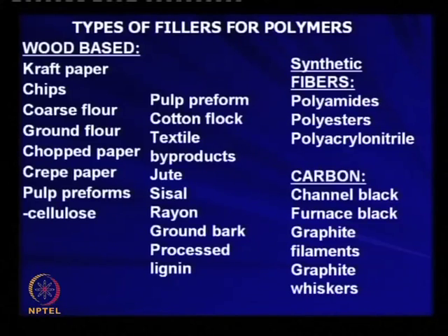You take some wood based material, either bamboo or softwood, that contains cellulose and lignin. Okay. There are pulping technologies, say xanthation technologies or cuproammonium technologies, these are available. So, when these chemicals are mixed with this wood, it becomes soft and viscous, and the lignin goes out, soluble things go out, and you get a pulp.